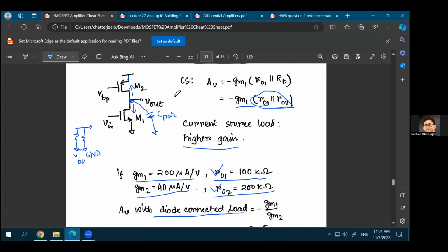Again, that's a good question. So the noise, it's not the fact that the devices are getting small and you have more noise because of that. It's not that. Noise will affect you when your signal is small, because eventually all you look for is the signal to noise ratio. If your signal is higher than your noise, you can always detect your signal. So signal to noise ratio is something that you want in any kind of communication, or if you want to do any kind of DSP, digital signal processing. All you look for is a high SNR, high signal to noise ratio.